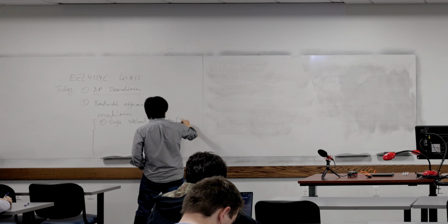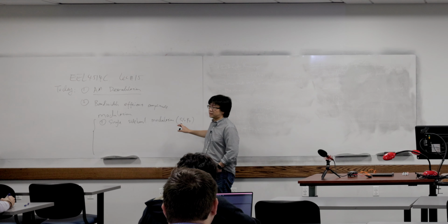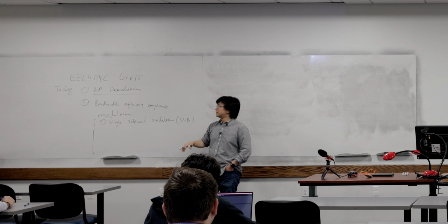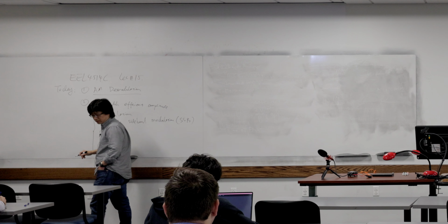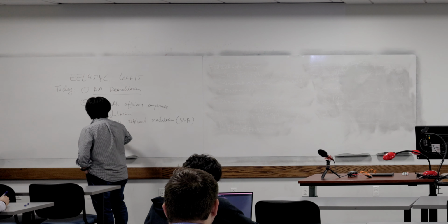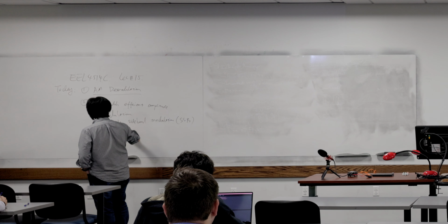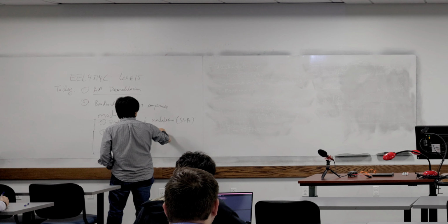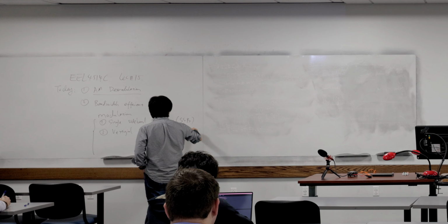Right, that's called SSB. In the single sideband, it may not be easy to do in practice, because it requires some higher order filter. So let's relax it a little bit. That is called vestigial sideband modulation, or we call that VSB.